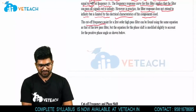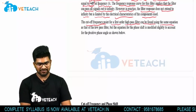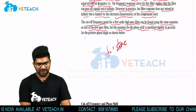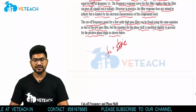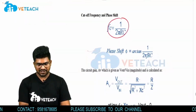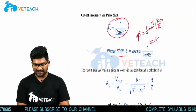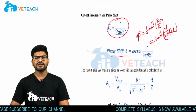The cutoff frequency of a first order high pass filter can be found using the same equation as that of the low pass filter, which is Fc equal to 1 by 2 pi RC, but the equation of the phase shift is modified slightly to account for the positive phase angle. In a low pass filter it is a negative phase angle, but in a high pass filter it is a positive phase angle. So the cutoff frequency is Fc equal to 1 by 2 pi RC, where the phase shift phi is equal to tan inverse of Xc by R, which I can write as tan inverse of 1 by 2 pi FCR. This is how we calculate the phase angle.